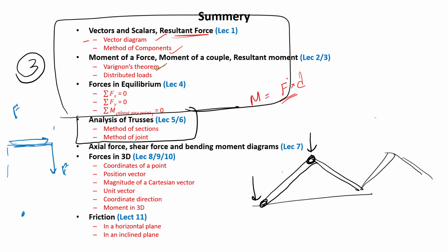So there are 2-force members, and we do truss analysis to find the truss member forces, their direction, and also tension and compression. There are 2 methods to do this, method of sections and method of joints. You have 2 questions from this as well in your final exam.